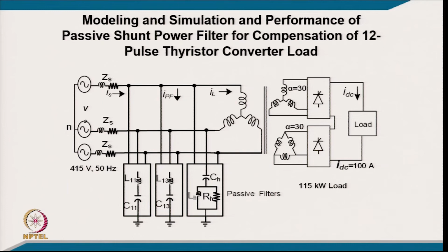I mean equal current certainly will help that balancing automatically of both the converter current, and then the voltage rating is increased because both voltages are connected in series. And the isolation is of course providing the right voltage, because in HVDC you go to high voltage. So, this we have from generation side to go to high voltage transmission system also, that is for HVDC, but for other applications also, I mean such kind of things.